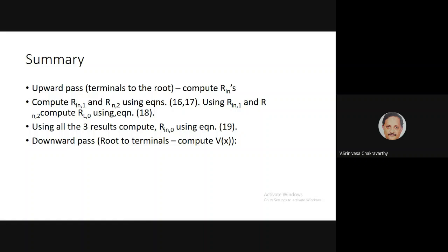So basically, the summary of it is this. If you have a big tree like this, let's say you have something like this, start with the far end from the terminals. Find the Rn for this one and this one, and apply the parallel formula. You can have multiple branches. It doesn't always have to be a binary tree; it can be an arbitrary tree. Start from the terminals, find Rn for all of them, and they're all sealed ends, so the Rn formula we know. They're all in parallel, so apply the parallel formula. You get the loading resistance of this cable,